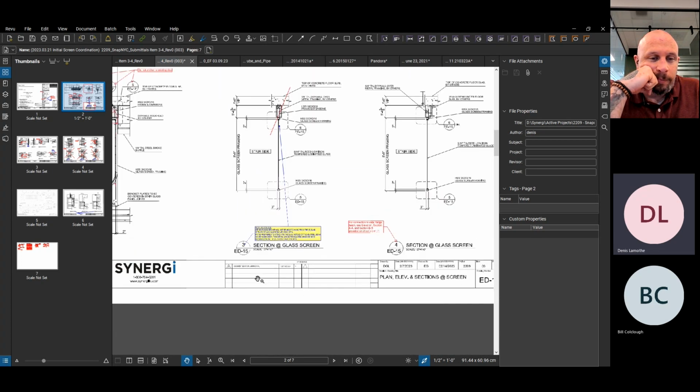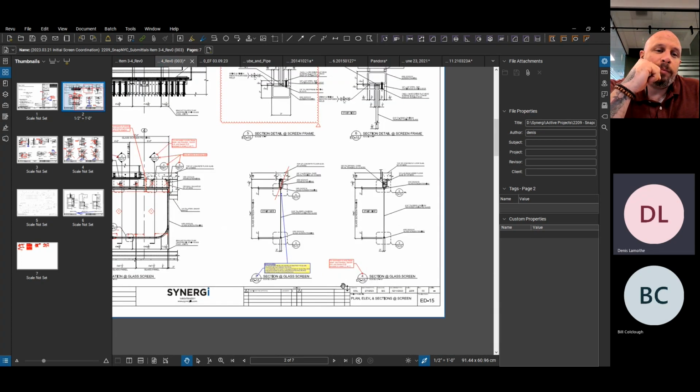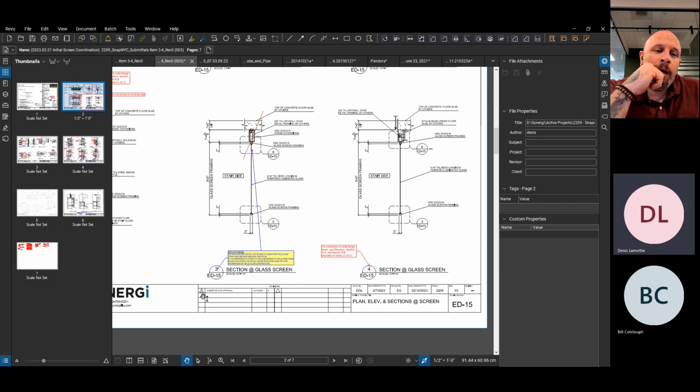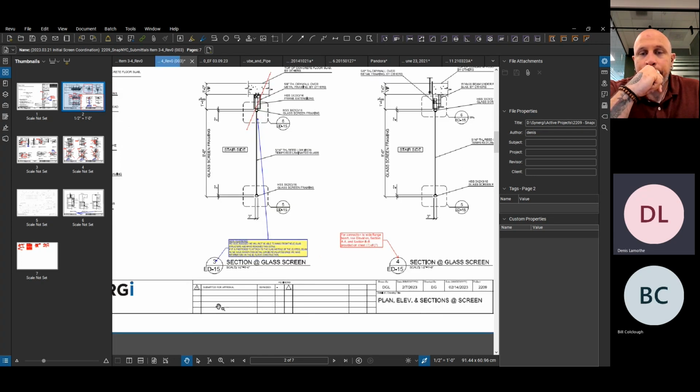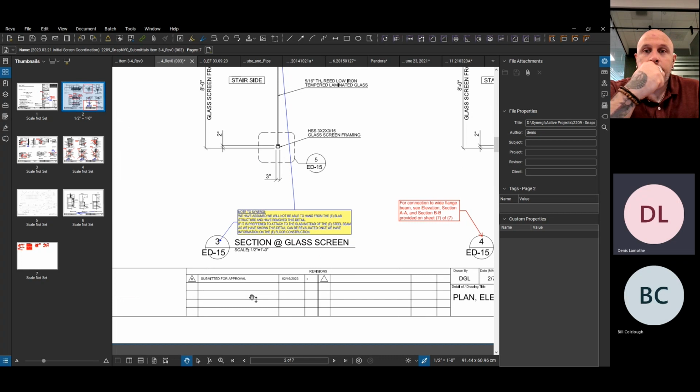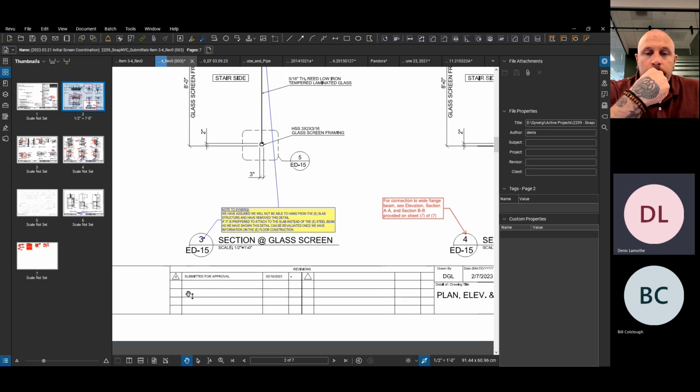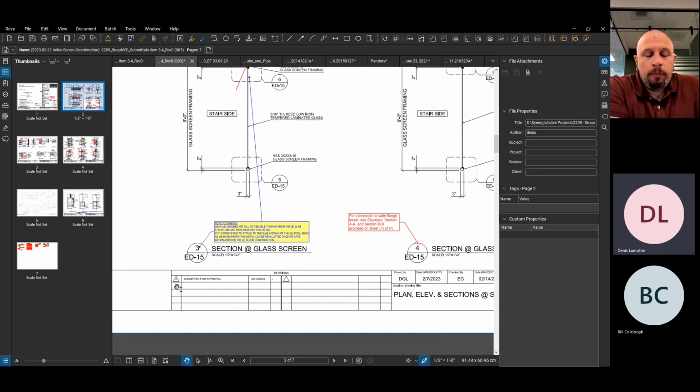It comes back to us marked up, red all over, kind of like this. I make these revisions and I'll send it to the PM and he or she will take a quick look at it. If they think there's something else they want changed, they'll bring it back to me. I'll make that change. But that series of changes would become revision 1 because we've received the drawings back from the client. And so any changes afterwards are automatically revision 1. It stays at 1 until we send it back to the client for reapproval if it's needed, or if we're releasing it for fabrication. So that's hopefully going to limit the number of times we're changing the revision numbers.